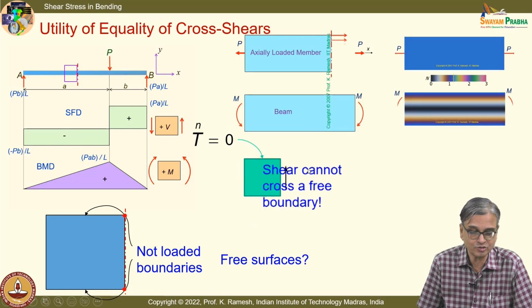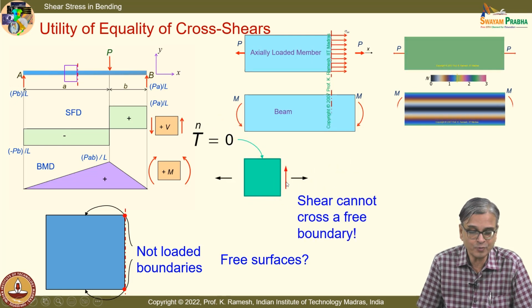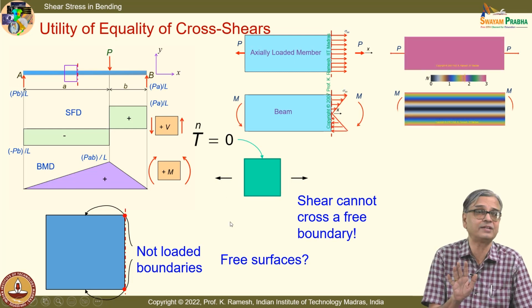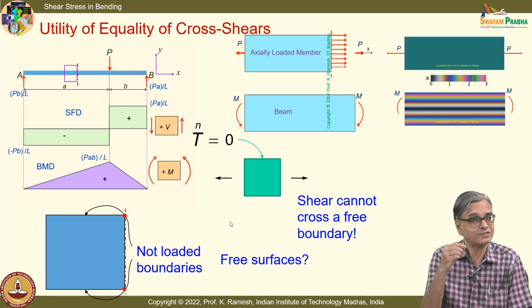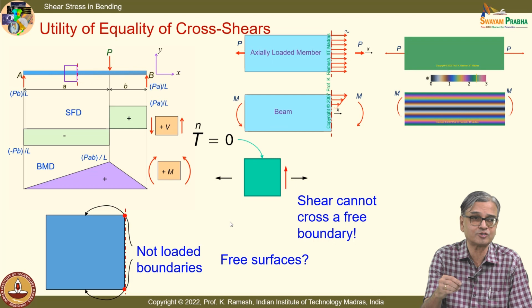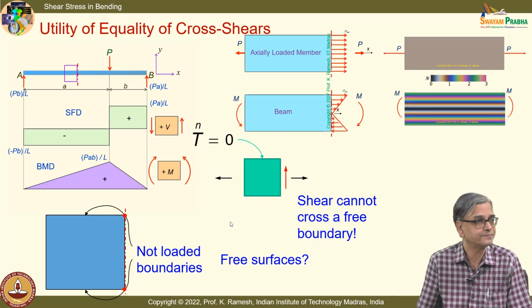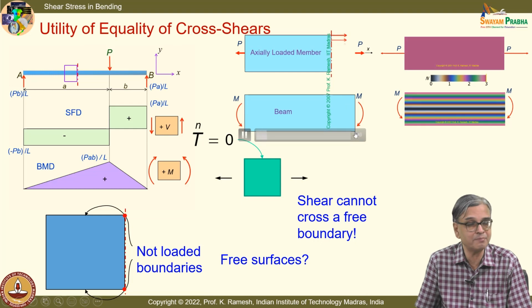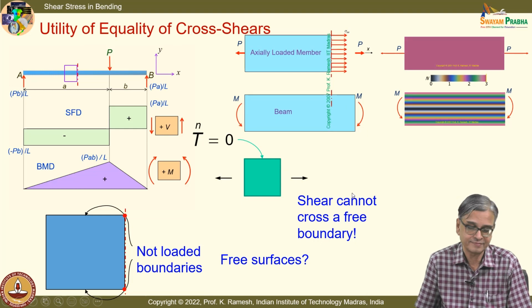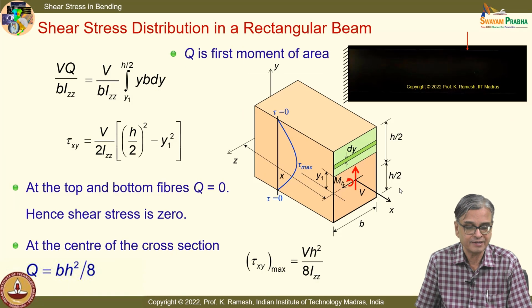And we also raised a question, can it support a horizontal force in this plane? All that is happening in the cantilever beam as well as this 3-point bend beam. We have seen shear stress is 0 at the top point and at the bottom point, and at the top point and the bottom point you have the maximum normal stress. So this conforms to that understanding.